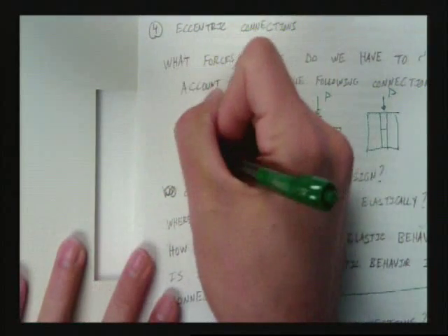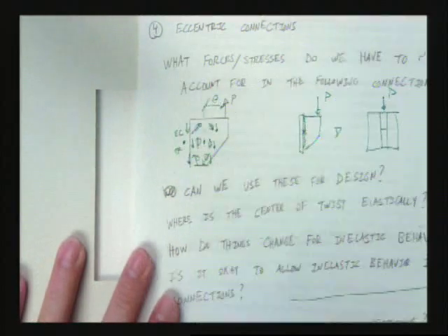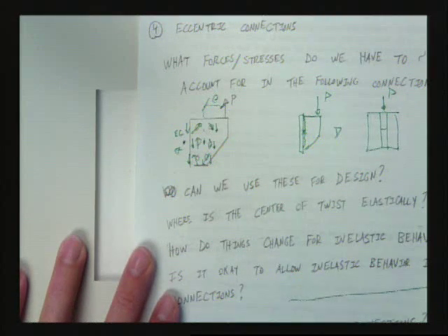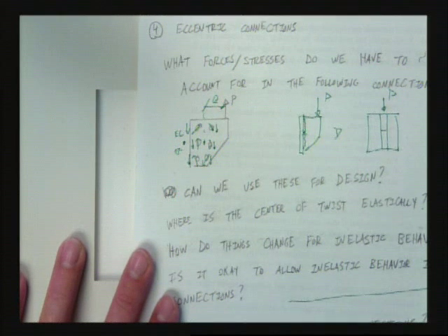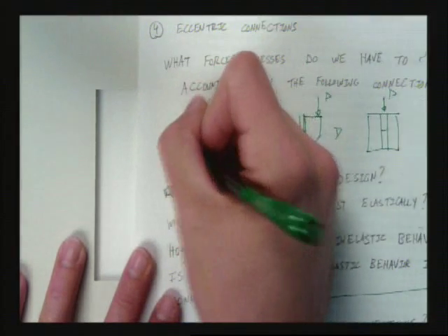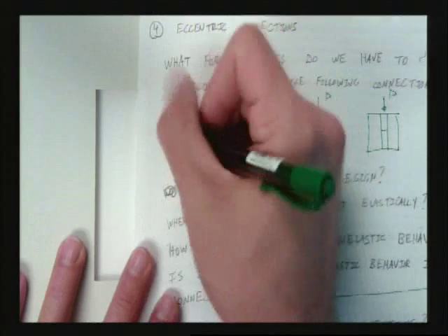And so the instantaneous center is actually going to be moved as we start to yield, much like the neutral axis moves between the elastic neutral axis and the plastic neutral axis. And I hope that's not the first time you've heard that. I know for the large majority of you it's not. Okay? It moves. Things give. And that's okay. So the elastic center is going to move to this point that we call the IC.